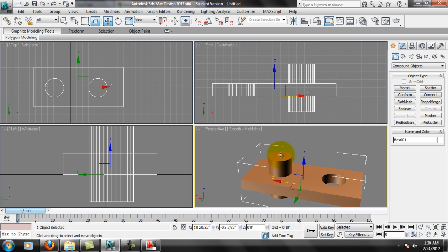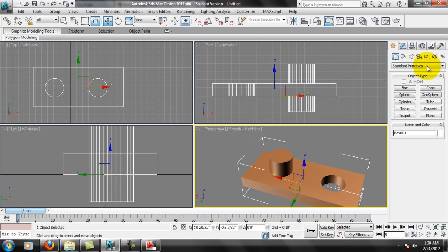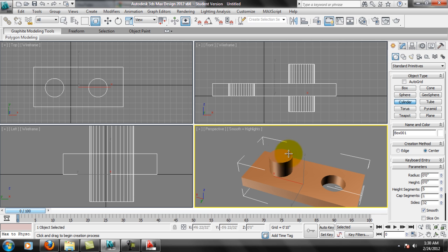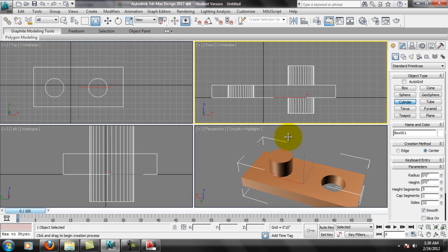If I want to draw on top of this guy here, I can come over here, standard, and do a cylinder. And the quick way, without actually creating new planes or doing the math, is turn on auto grid. And you'll notice that I automatically switch to on top of this face. I switch to whatever face I'm on. So auto grid will allow you to snap to those faces and draw on those faces. That will help you with some shortcut as far as math goes.